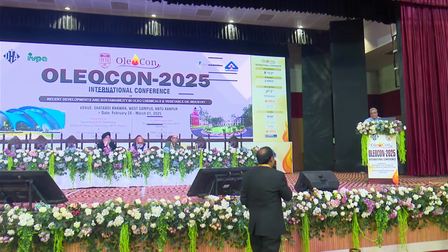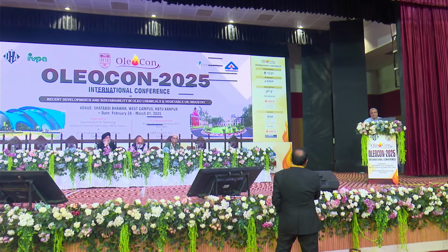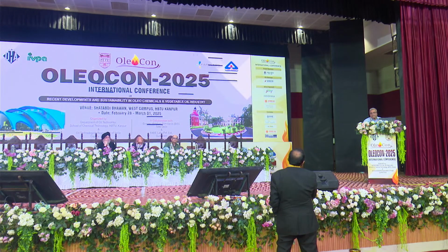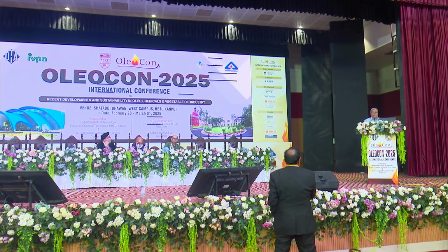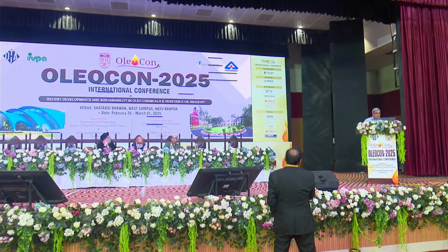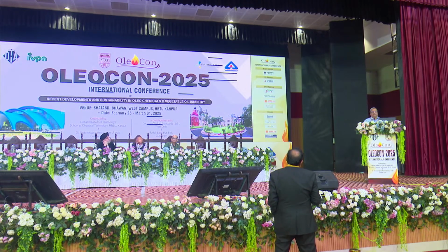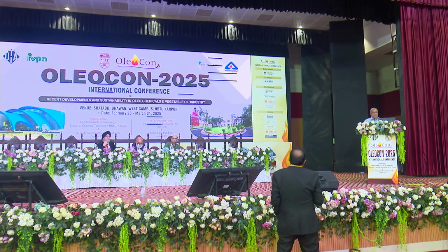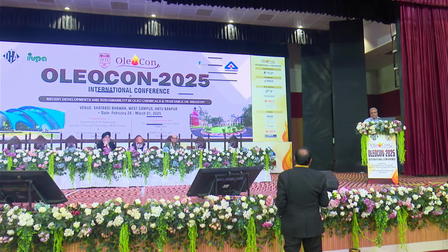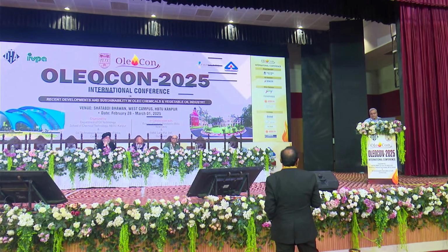What about the final oil color? Are you getting 8 unit, 10 unit? The soybean standard is 8 to 10 unit maximum. Is there any data available with you? Final oil color for those high chlorophyll oils, people maintain between 10 and 11 units. It is different for different standards, but it is maintained at 10 to 11 units.